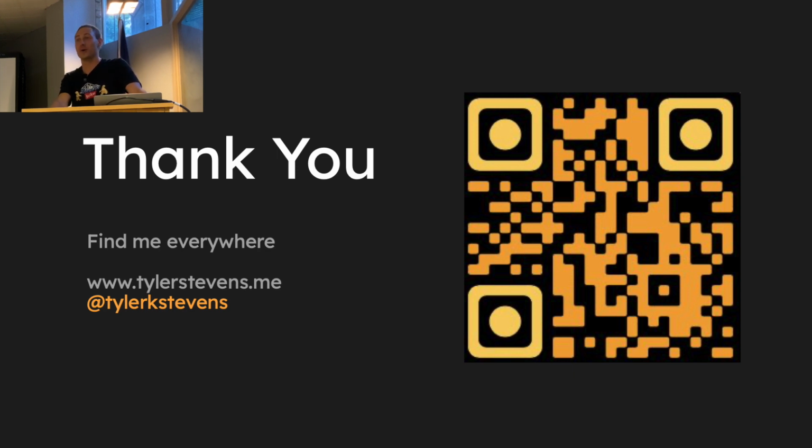What I've learned from guys like Scott, who developed the BitAxe, the Open Source Miners United group, is that smaller transistor sizing, nanometer processes, are more efficient. Your distances between transistors are smaller, so it takes less energy to move electric current around. You can run into leakage current, is that right, David? So you can get errors at higher temperatures. Basically, you can run into thermal runaway, and then the chip is going to smoke.